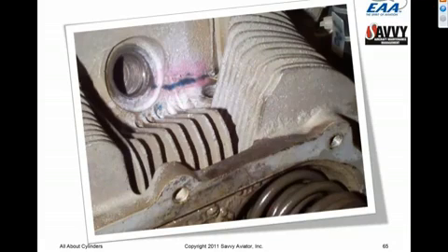We frequently will get reports from mechanics of a cylinder head crack that turns out not to actually be a cylinder head crack. So anytime a shop reports a cracked cylinder head, before we let them pull the cylinder off, we require that they do a dye penetrant inspection and send us a photograph. And if there really is a crack like there was here, it will be completely obvious after the dye pen is sprayed on.